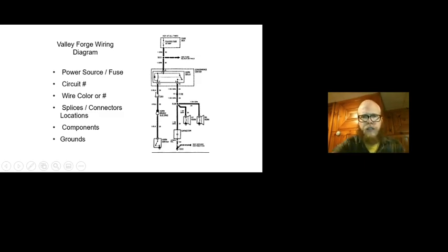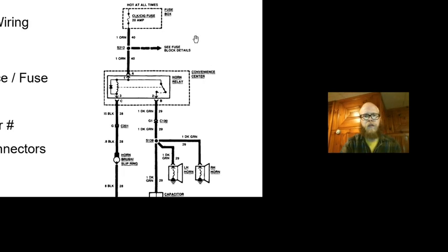We also can see, I'm going to zoom in a little bit, so we can see my splice number. It's number 212, and I could actually look up that location online. I also am being shown the color of my wire, orange, I would imagine, and the circuit number. This is circuit 40. Circuit 40. We come out of the relay, now we're circuit 28.